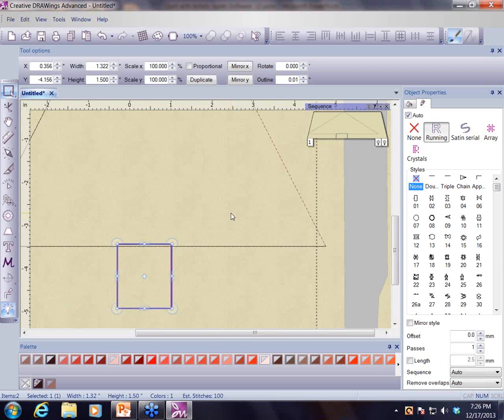It's going to kind of hold those together to where one can't get out of whack with the other. I also want to change the width between the two of them to 1.5. So I'm going to come up under here and type in 1.5 and enter on the keyboard. And that kind of pushed them a little bit a ways from each other.